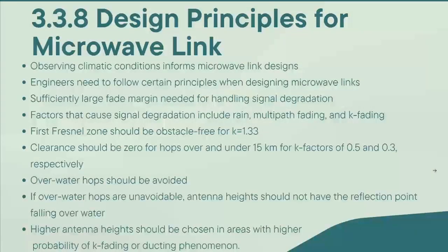So after understanding the topic of fading, we should also understand the design principles for microwave links. Observing climatic conditions informs microwave link design. Engineers need to follow certain principles when designing microwave links, including a sufficiently large fade margin needed for handling signal degradation. The first Fresnel zone can be kept obstacle-free for K equal to 1.33, and clearance should be 0 for hops over and under 15 km for K factor of 0.5 or 0.3 respectively.